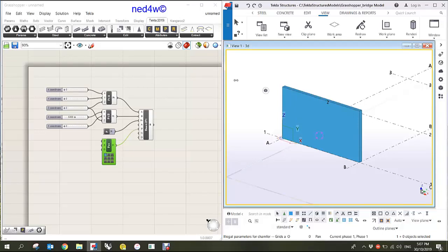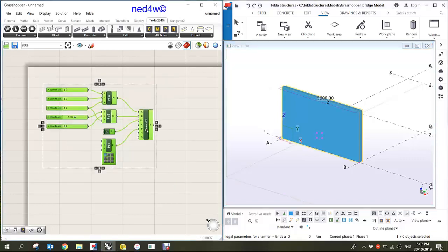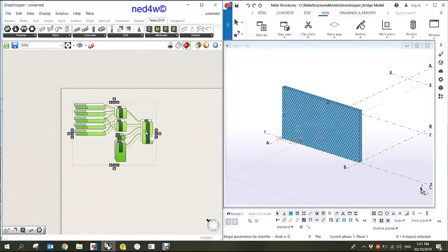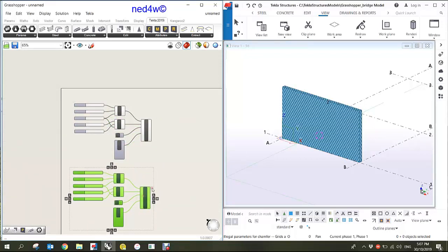So at this point of time, I'm going to copy this and then use the next element as my opening. So select the whole thing, Control C and then Control V, and then put it down. Now if you notice here, because I duplicated that one, my beam is also duplicated here.